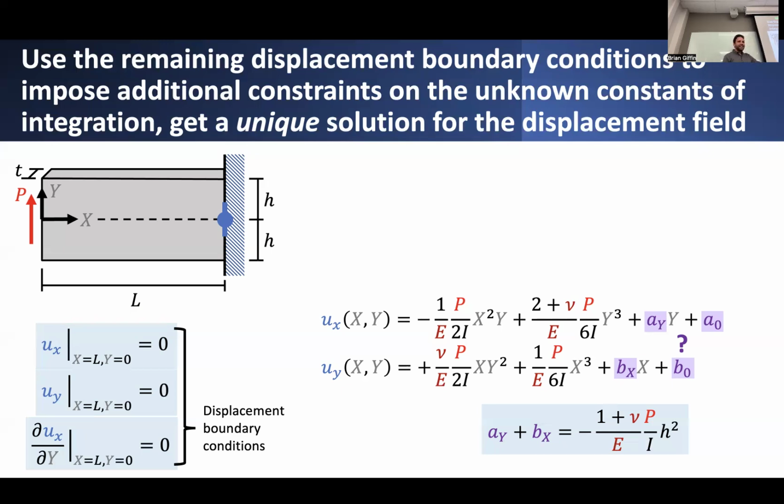this kind of funny representation, the partial derivative of ux with respect to y has to be equal to 0, is tantamount to saying that this line segment, oriented somewhat vertically, can't rotate. That's basically what this equation is saying. And you can stare at this and rationalize why exactly that is the case. But you can think of the rate of change of ux varying with respect to y as being an indication of how much this line segment is oriented relative to vertical.